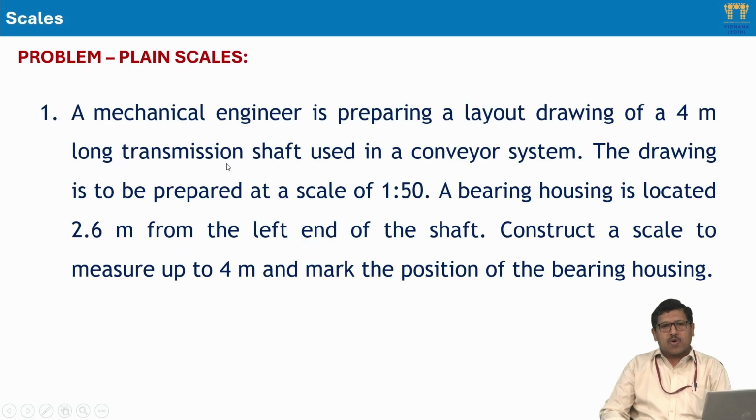Now we will go through this problem statement on how to construct the plane scale. So what is the statement? A mechanical engineer is preparing a layout drawing of a 4 meter long transmission shaft used in a conveyor system. The drawing is to be prepared at a scale of 1:50. A bearing housing is located 2.6 meters from the left end of the shaft. Construct a scale to measure up to 4 meters and mark the position of the bearing housing.